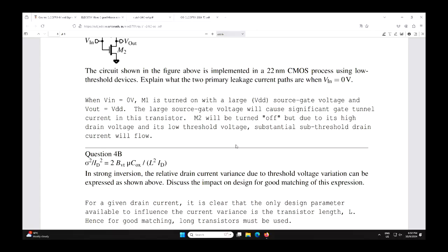Well, I guess that's what you will have to do. If you think of the length as fixed, that's not something you want to fiddle with, then you've got to increase the current, which means that you make the transistor wider, because in a digital circuit the voltage is given and is not something you can fiddle with. So that would be what you have to do.